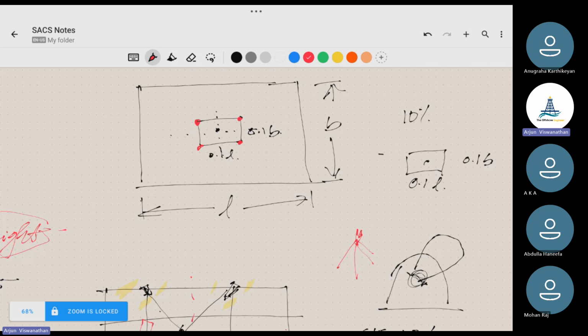So what happens is, once they fabricate everything, they will do a trial check and the COG is matched. If they want to say it is acceptable, we need to do this COG lifting case within this envelope. Now, let's say when they fabricate, the COG comes outside, that means we again need to do this analysis considering, okay, COG came over here, so what happens if I put the sling over here?